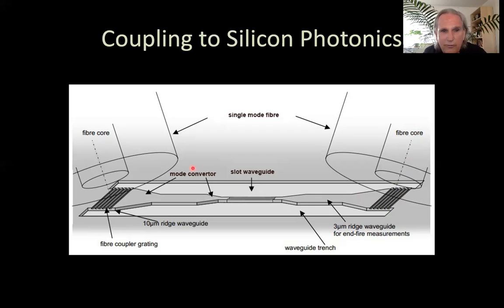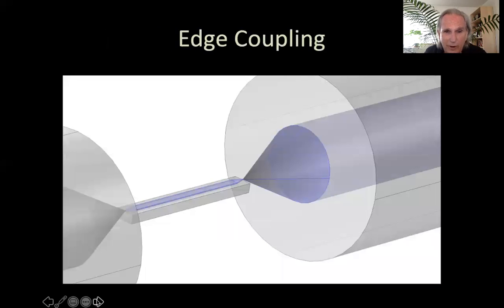Coupling out is easier than coupling in because you have to find the waveguide. These things here had a minimum of 3 dB per channel in order to couple light into the silicon photonics. So the loss budget is worse in silicon photonics than in fiber optics.